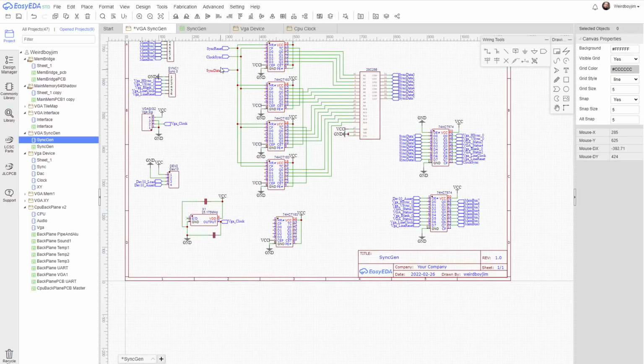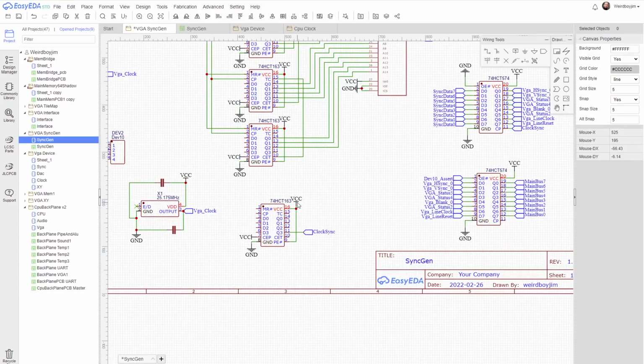Okay, so we're going to take the sync clock out of Q3. So that's the divided down clock we want. This one, the master reset, we're just going to tie high. CET needs to be high as well. The other outputs are unused. But these data inputs, they will need to come down to ground as well.